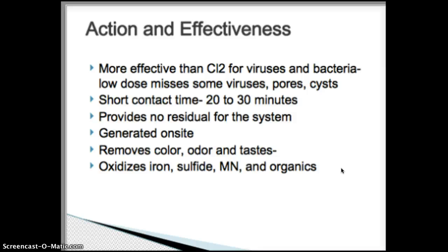Ozone is a very powerful oxidant used in treatment for color, taste and odor, organics, algae, cyanide, hydrogen sulfide, iron, manganese, heavy metals, detergents, and as a preliminary disinfectant. It must be followed with chlorination to provide a disinfectant residual in the collection system. Since ozone cannot be stored, it must be generated on site as needed.